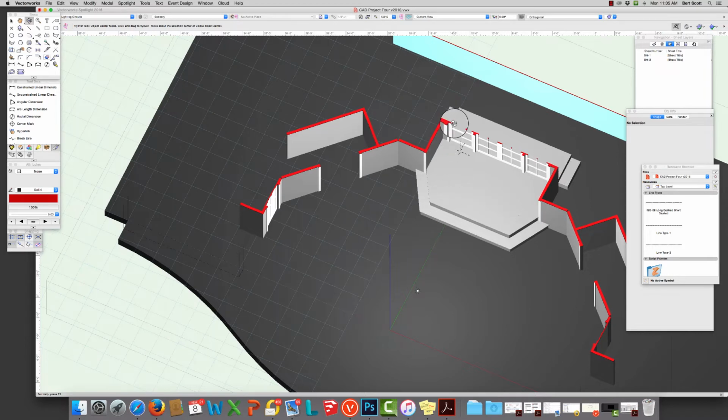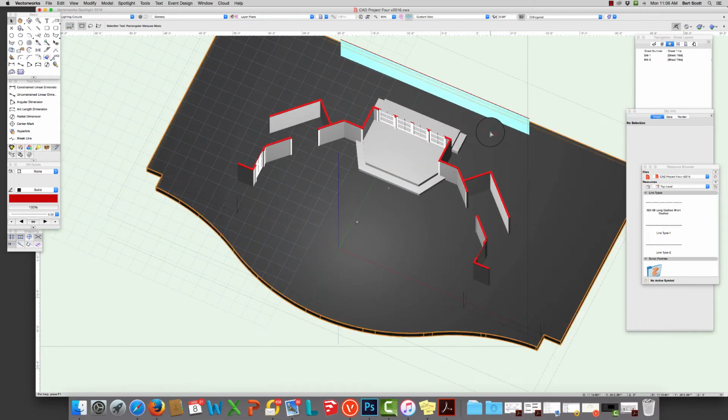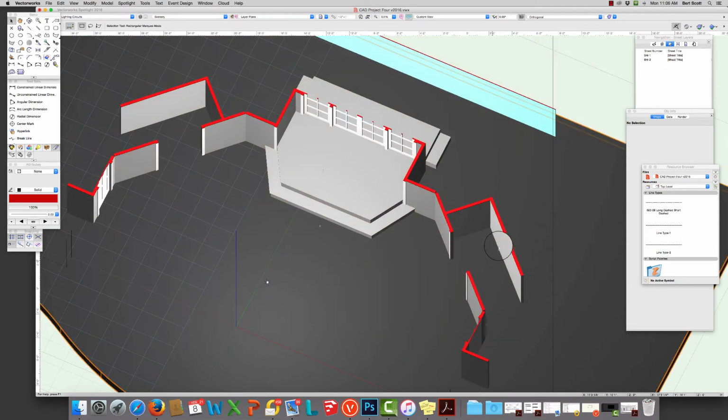Then we have this wall that's got a window here, and then 2 doors, and then a window. So if you just look for the symbols for door and window, realizing though that these doors are actually windows, you replace the part of the door symbol that's actually the door with a window, which is how you show a French door like this. And then this side of the set is symmetrical.